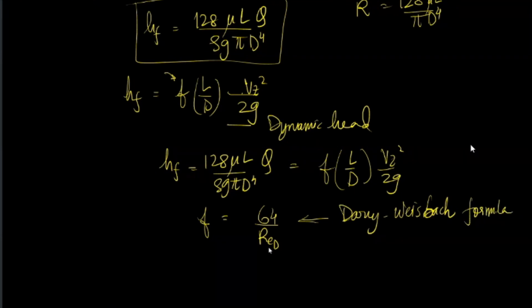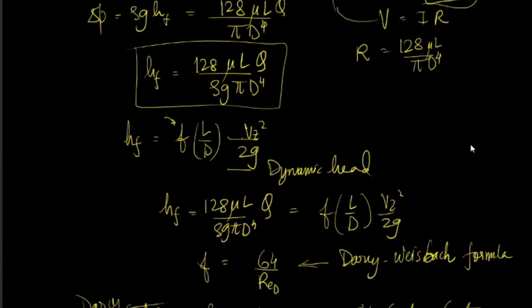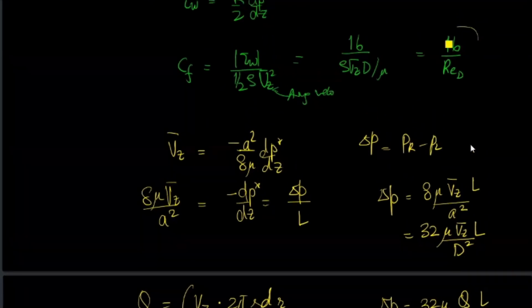So from this we see that the Darcy friction factor, as it's also called, is equal to 4 times the skin friction factor. We've just obtained that the skin friction factor is 16 by Re_D.